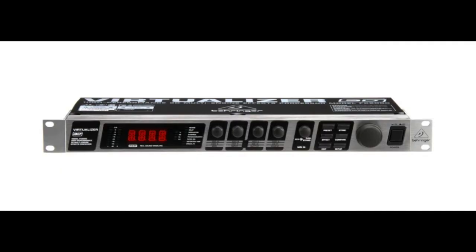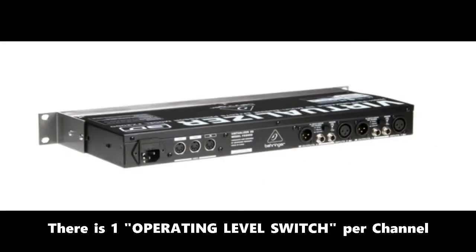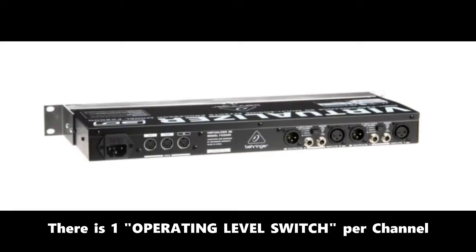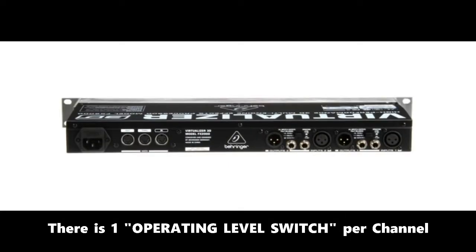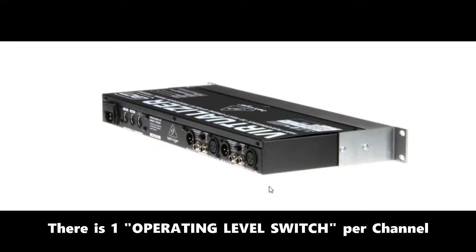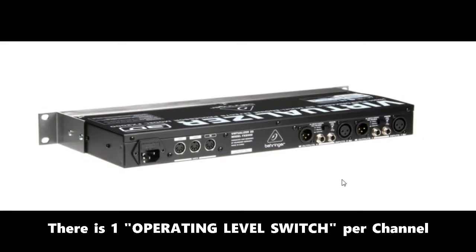On the back of the unit, we did talk about this during our technical specifications, but we do want to look at the switch that you can use on the back of the unit that will allow you to switch between a negative 10 dBV, which is the home recording level, and the +4 dBu, which is the professional studio level. In order to switch between the two, you're going to use the operating level switch. This is on the back of the unit. When you switch between the two, the level displays are changed to the nominal level, and then the unit, of course, if you switch it to the +4, the unit operates in its optimal range.